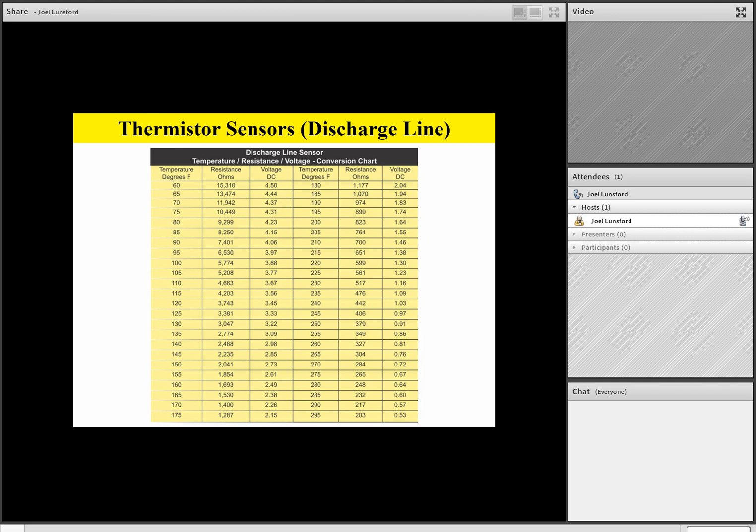So remember, team, as a final review on sensors, there's 3 tests. You're going to check to make sure the board has 4 to 5 volt DC without the sensor plugged on. You're going to unplug the sensor and take the temperature that sensor is subject to. You're going to unplug the sensor and then ohm the sensor out, or look at the resistance in ohms on the sensor with it unplugged from the board. You'll then plug the sensor back onto the board and read the DC voltage of the sensor plugged back onto the board.